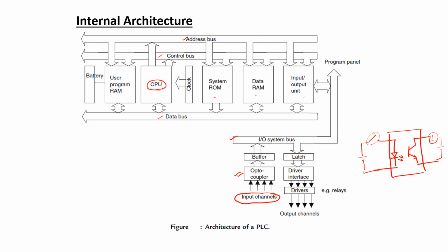In general, an optocoupler works similar to a relay, but instead of using an electromagnetic coil and mechanical contacts, it uses optical devices in the form of an LED and a phototransistor. So there is separation between different circuits, but the different circuits can be coupled optically using the LED and phototransistor.